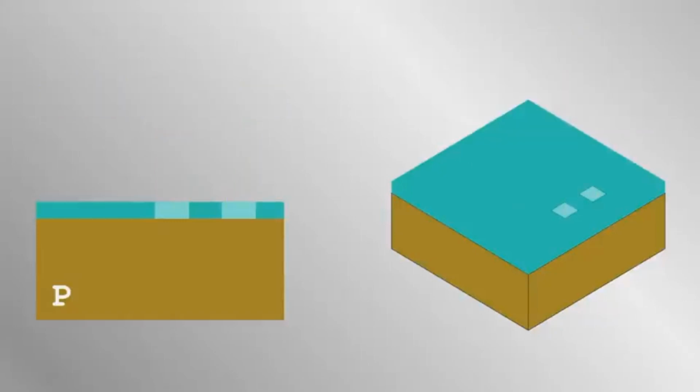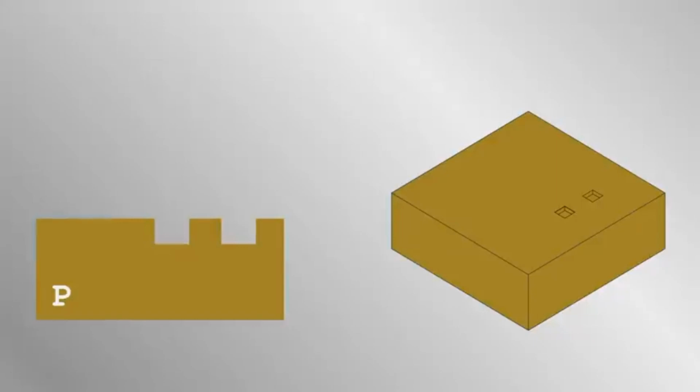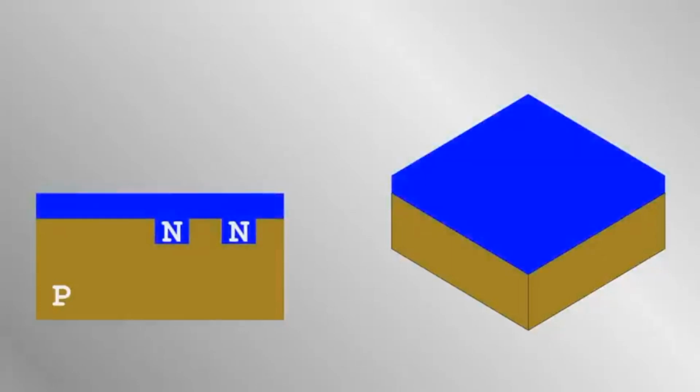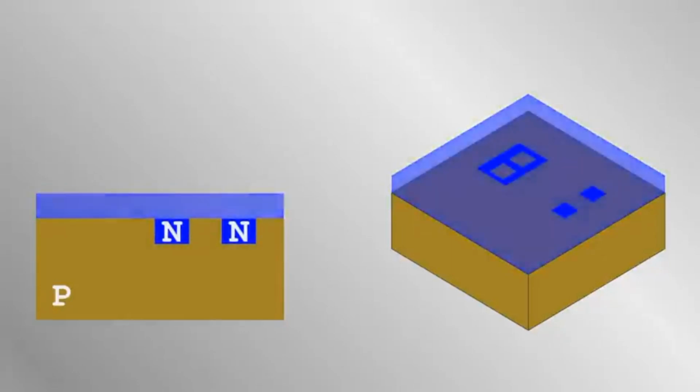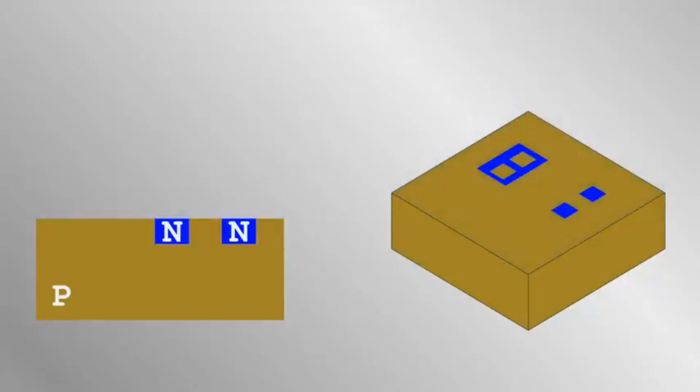A special etching method is used to remove only regions of photoresist which were exposed and nothing else. This opens up gaps in the photoresist, and then another etching method is used which targets everything except the unexposed photoresist. Finally, the remaining photoresist is etched away. As a result, material has been removed wherever there are any gaps in the mask. The two techniques of deposition and etching used in conjunction mean that the n-type dopants for all the transistors on the die can be added simultaneously.